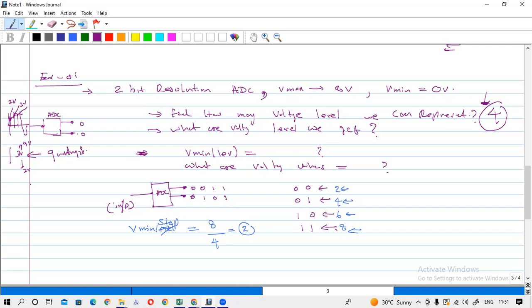So you have to sample the signal. That means you are getting some voltage value. Then you have to quantize them. That means you are going to approximate them to an encodable voltage value. In this case, if you have sample voltages 2, 3, 4, 5, 6, 7.5 like that, you have to approximate these to an encodable level. So encodable levels are 2, 4, 6, 8 in this case. So you can represent this 3 by 4 or 2.